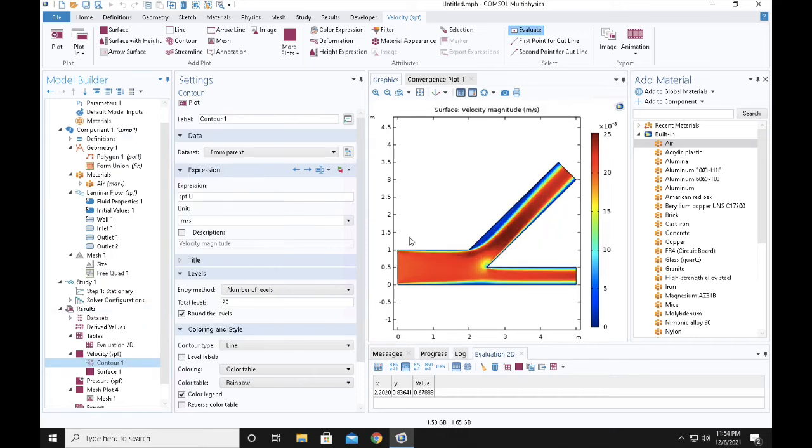Okay, so this one's the velocity contour, and over here we can see that the inlet velocity is in the region of 20 times 10 to the power of minus 3, which is 0.02 meters per second. We can also see that along the boundary the color is blue, which is almost 0 meters per second. This is due to the no-slip boundary condition, so we can understand that the fluid flow is following the no-slip boundary condition. The next graph I'd like to discuss is the pressure graph.